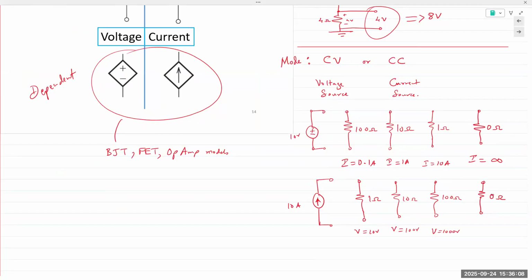Not if it's the power supply. If it's anything else, like it's just a point in a circuit, then yes. So the answer to your question is yes and no. If it's any other circuit, you simply have 2 points in a circuit you want to send current through, then yes, you can run a current through a short circuit as long as it's part of a larger circuit. But if it's your power supply and you just short the terminals, then that's a no. We don't want to do that.